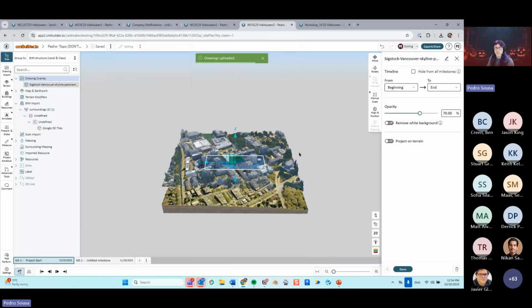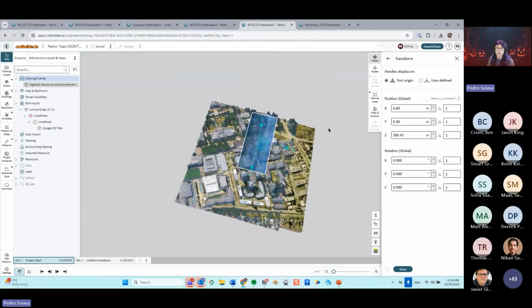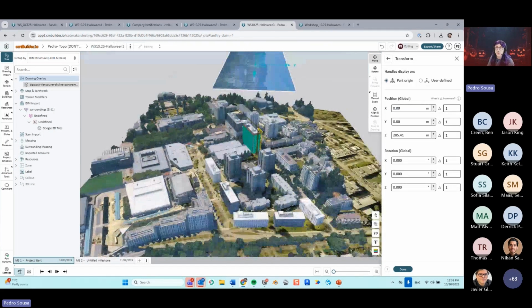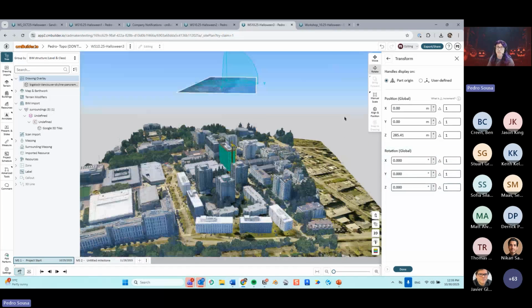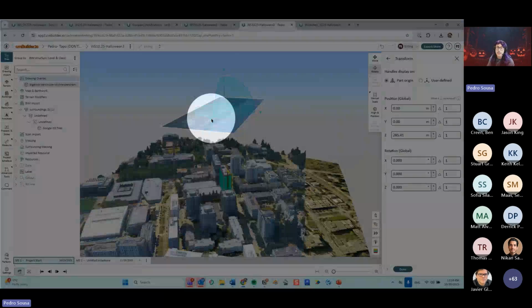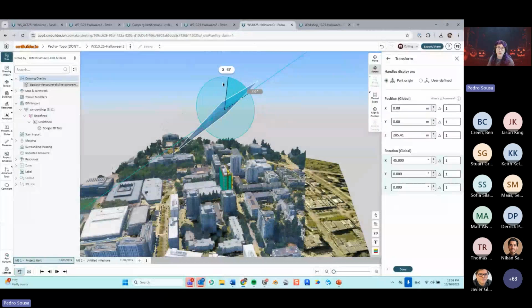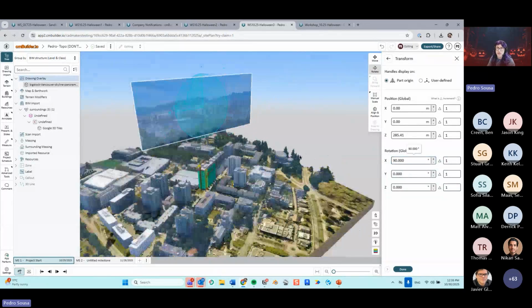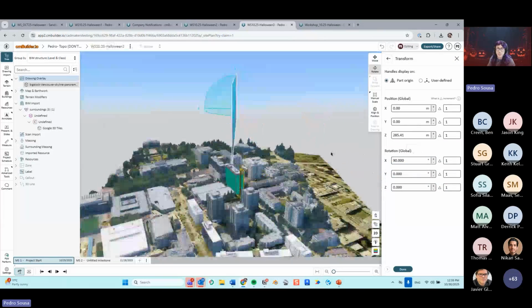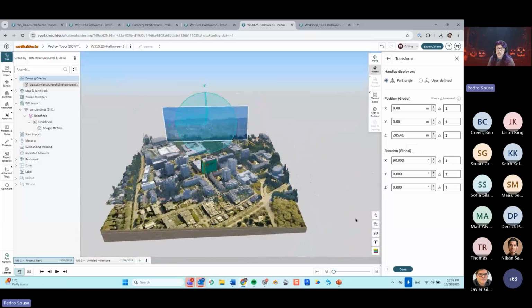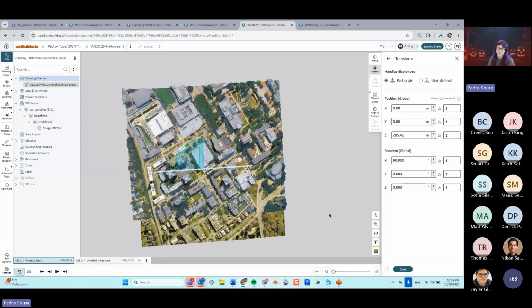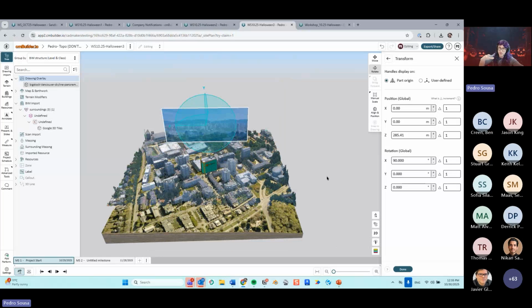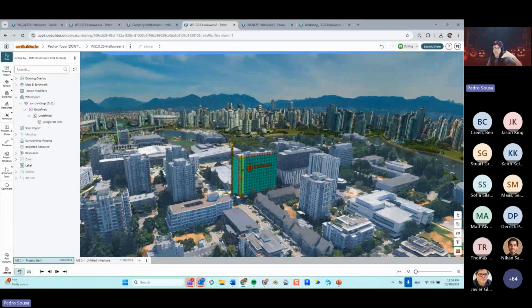First of all, the images will always come flat on the ground like this, right? So the first thing we're going to do is rotate, and I'm going to rotate in the Y direction. I can either hold shift and rotate this manually, or I can just type in 90 degrees over here, and then this image will rotate, okay? So now it is just a matter of scaling it. I like to scale the image a little bit bigger than the map itself, just to get that sense, that effect of things being in the distance when you zoom in like this, right?